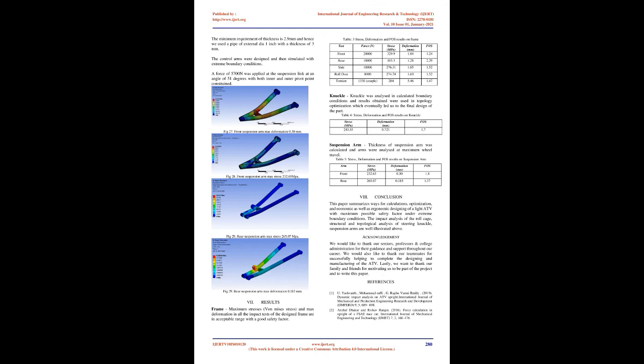6. Suspension arms. The selection of suspension geometry is done to fulfill our requirements with the minimum material application. A double wishbone with dual A-arm, with a damper to the lower wishbone, is chosen for the front as it has the advantage of more variation in toe angle, camber angle, and caster angle. For the rear, H-arm with camber link arm is selected due to its robust structure and lesser material requirement and fulfillment of requirements of rear suspension geometry.